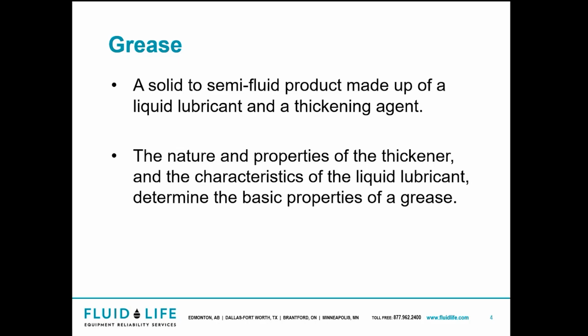So whether you have a super thick grease, like a clay grease, or a very thin grease like you would see in central lube systems, it's the oil within that grease that still does all the lubricating. The thickener is just a way of transporting the grease to your components.